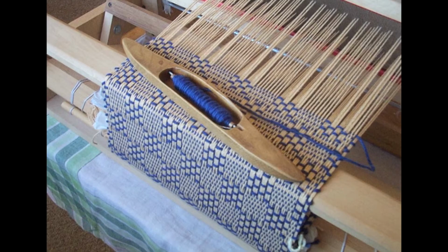The small weft package in the shuttle requires frequent replenishment. The pirn that is inserted inside the shuttle can carry only a limited amount of yarn. Now when this weft yarn is exhausted or over, it has to be replaced with a fresh pirn. Here there is a stoppage of the loom. Again the loom has to be stopped, the pirn has to be changed, and then the loom starts again. Here again there is a lot of wastage of time.